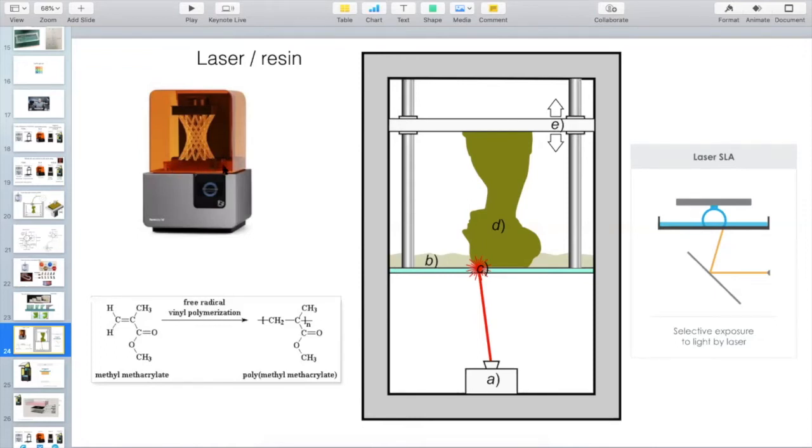Here you have your liquid resin that is 99% made out of acrylates. And on the bottom, you have a laser that photocures this resin. So you harden the resin just by shining a laser of 405 nanometers. And you have the stage, this part here on the form, and this stage is moving upwards.